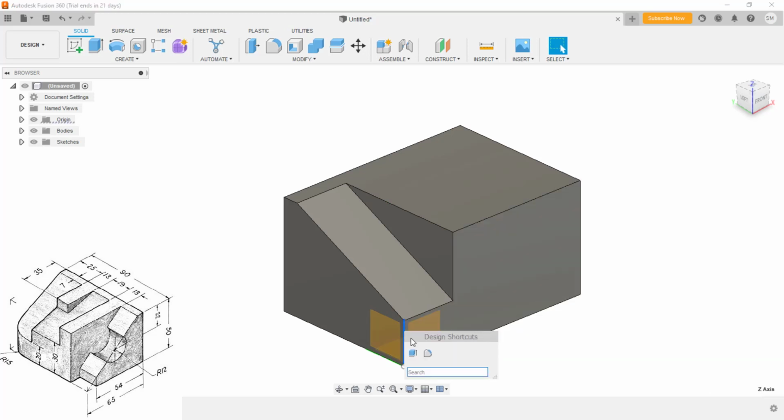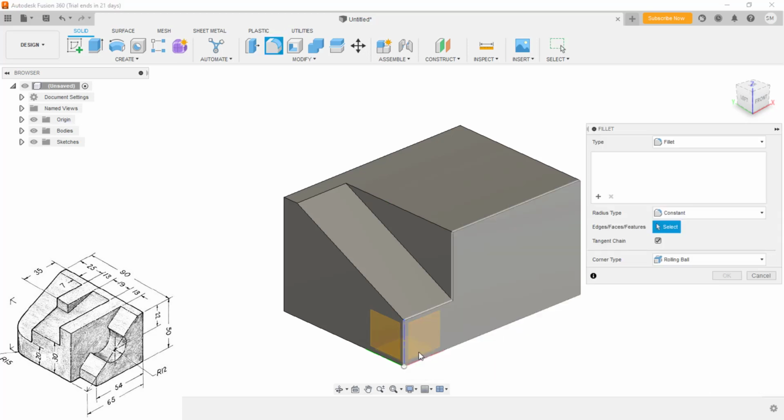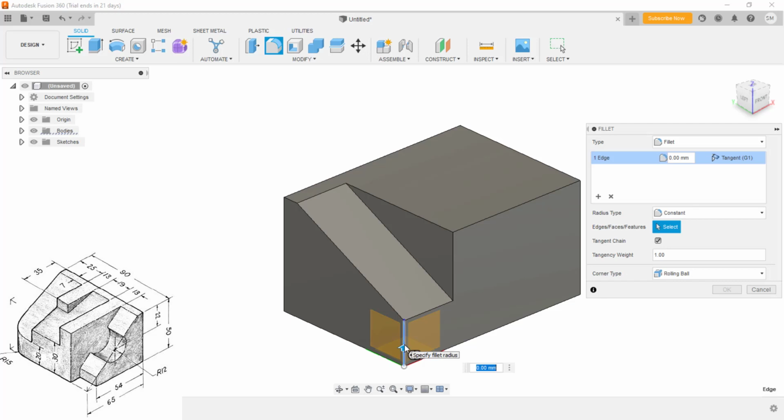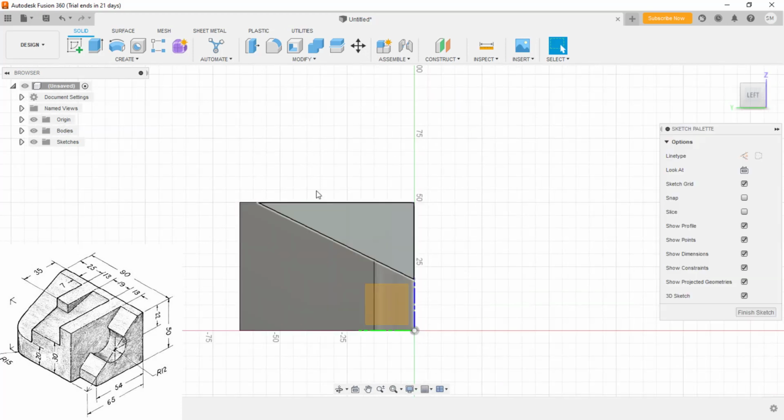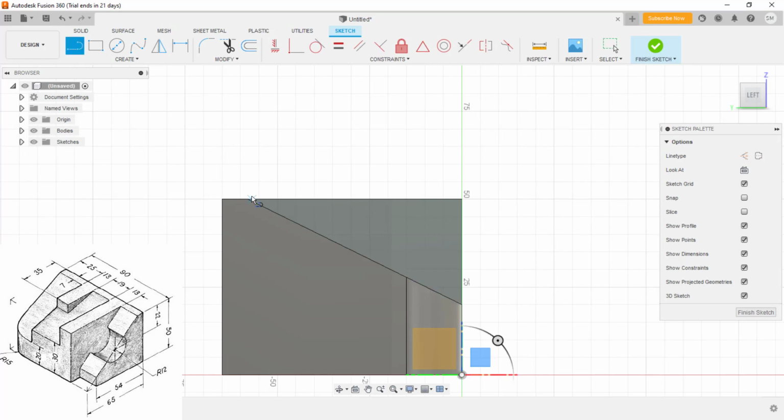And now here I need the fillet. Then, sorry, it is fillet, right? Directly it is available. No need to switch for chamfer. The value it is ready is 50. This face I'll sketch. So here instead of sketching only one, I'll use both contours so that I can use it later on. Let me refer this point as a reference, and I'll draw the triangle again like this.